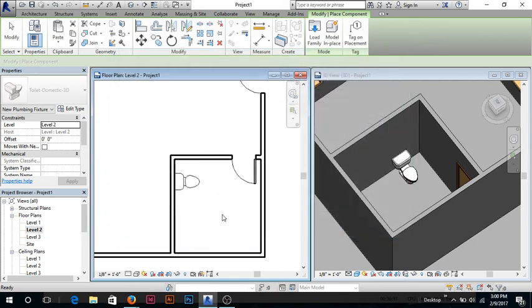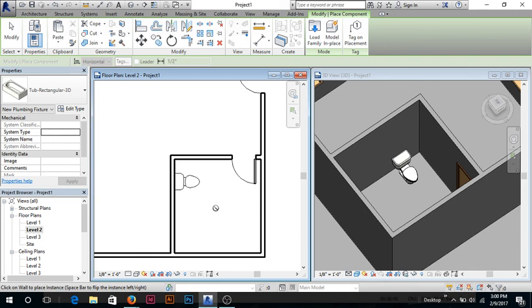Open. So you have this little stop sign looking thing. What that means is you cannot place it. Why? Because you're not against the wall. Now watch this. If I slowly snap, it's slowly going to show. So I can't place it in the middle of the room. There's some components that work like that as well, so always keep that in mind. If you click on a component and it's not popping up, that's probably why, because you need to snap it against the wall or some sort of component that it's only registered to. So in this case, I'm going to snap it to here, and you know what? I want my drain to be on the other side, so simply spacebar, flipped it. Awesome, perfect. So I can place it, escape, escape, and here we go.